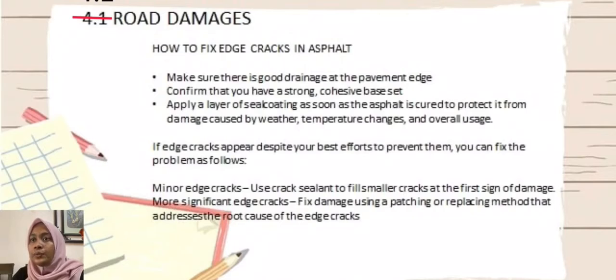First, make sure there is good drainage at the pavement edge. Second, confirm that you have a strong, cohesive base set. Third, apply a layer of seal coating as soon as the asphalt is cured to protect it from damage caused by weather, temperature change, and overall usage.